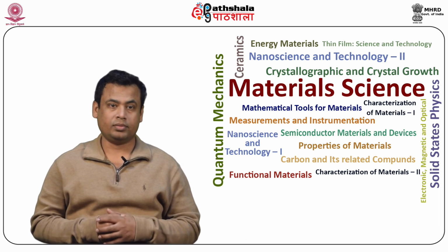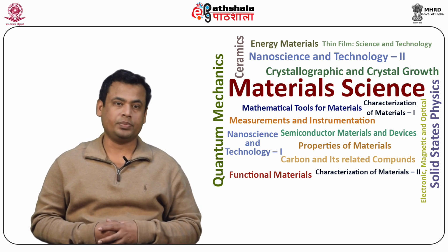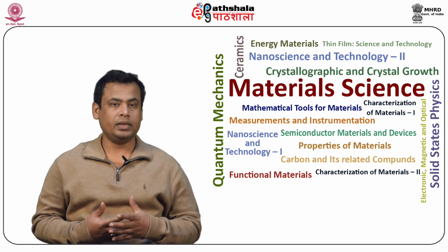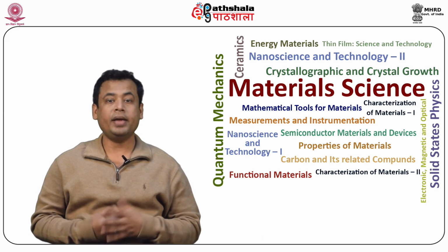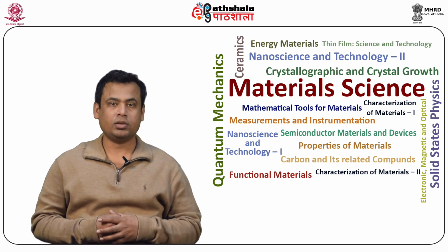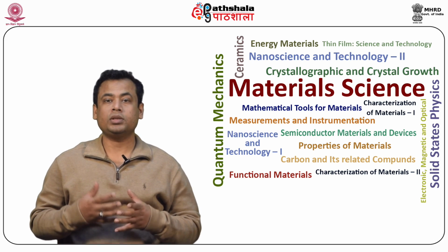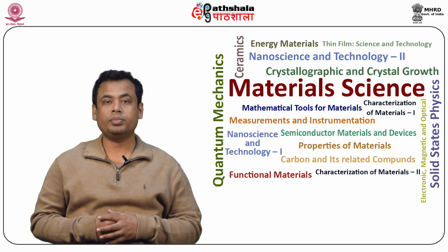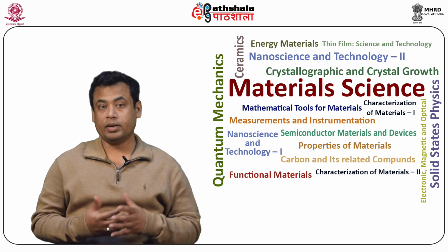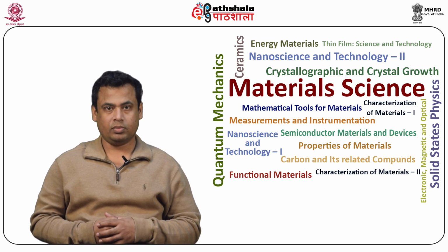Third is the ion gun. The function of the ion gun is twofold in XPS. Firstly, it provides high energy ion flux to clean sample surfaces before examination. Sample surfaces are commonly contaminated with adsorbed hydrocarbons, water vapors, and oxides that need to be removed before surface analysis.